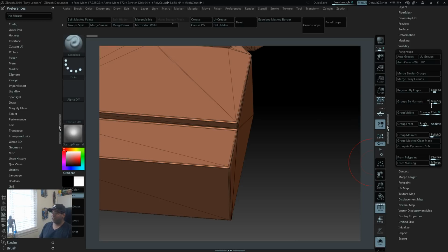But one of the things that you can do is probably, it'll start by a default of an angle of 45, but usually I start with something a little bit lower, like maybe 8 to 10 degrees, or let's say 10 degrees, or 12 degrees, right? Lower number. And then I will group by normal.